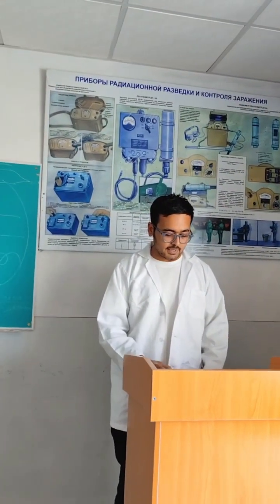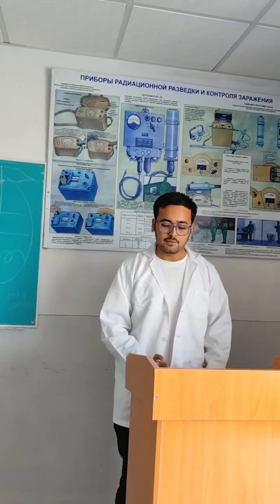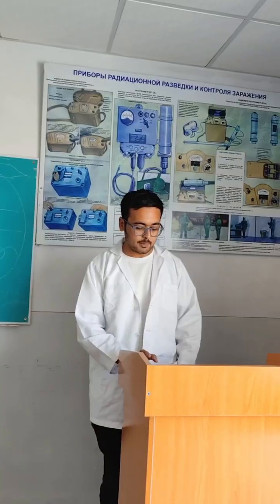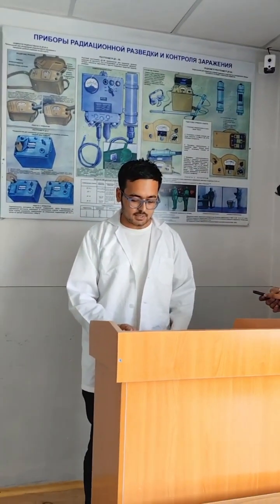safety. Natural lighting with windows facing southeast for maximum daylight. 1:5 windows to floor area ratio recommended. Prevents growth of microorganisms, improves patient recovery and staff efficiency.